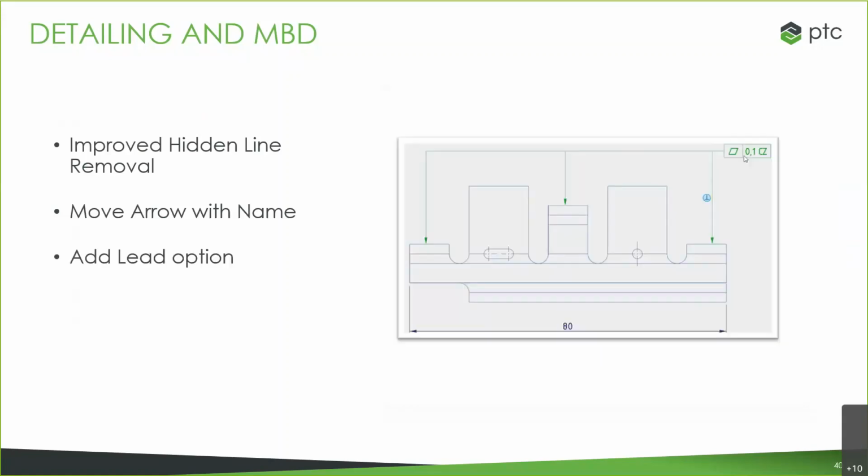And now we also have the ability to add multiple leads. There's an option where you can have multiple normal tangent leaders all coming off of one common annotation. So it's really helpful for GTOLs, notes, symbols, anything around that.